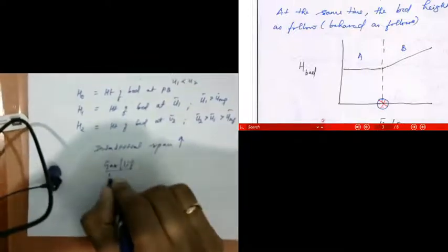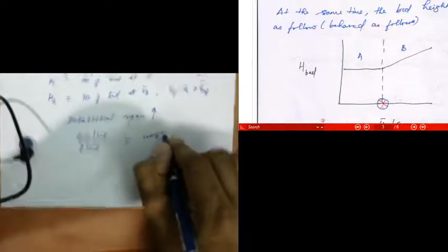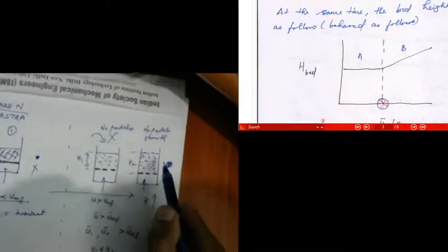So when the gas is continuously pumped inside, these particles don't settle. So that means the gas or the liquid, or in general the fluid, supports the weight of the bed, or rather this upflow, the drag of the fluid flowing upward. So the force due to the fluid flowing upward balances the net weight of this bed. Is it clear? It balances the net weight of the bed.